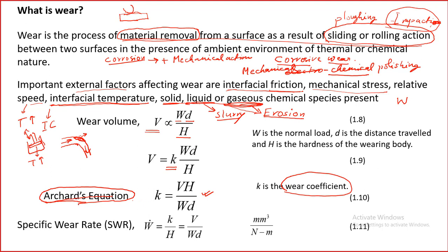So please remember this Archard's equation. What will be the units of K? Dimensionless, sir. Yeah, it is dimensionless. This is also very important to remember that this K, which is known as wear coefficient, is dimensionless.